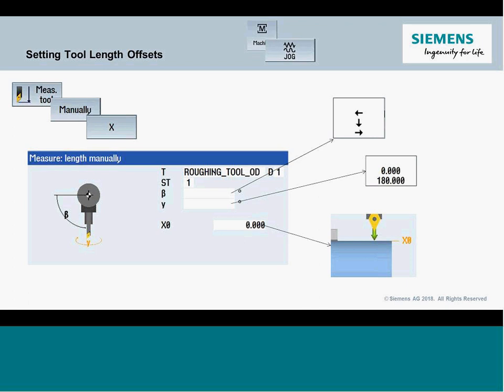So what will happen is if I have the arrow pointed to the left, that would be just telling the beta to go to that 0 base position. If I have a down arrow pointed, it's going to go to 90 degrees of the B-axis. If I have a right arrow, it's going to go to 180 degrees. So just shortcuts to move this thing around a little bit. Certainly the gamma is going to be the positioning of the spindle. So the 180 is automatically going to propagate there, or if I choose the blank one, just like the blank in the beta, I can type in whatever angular value I need.